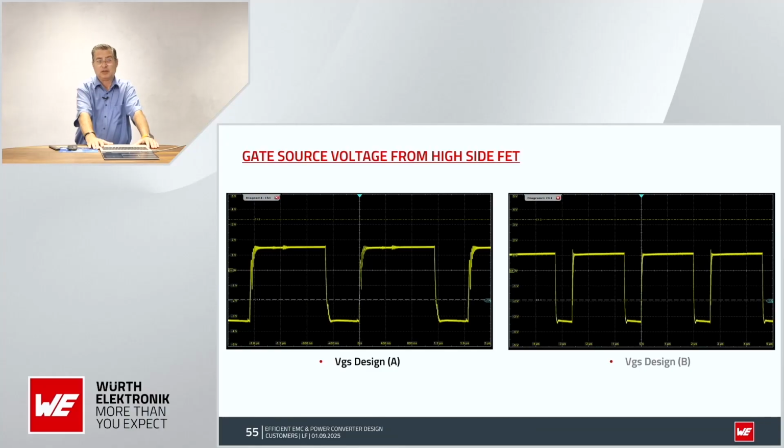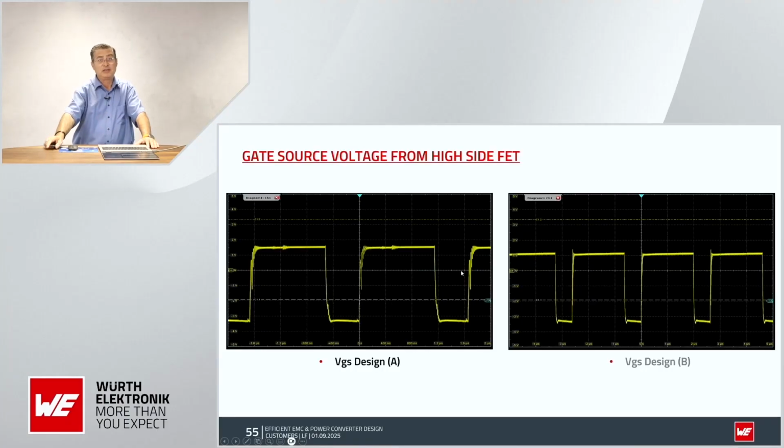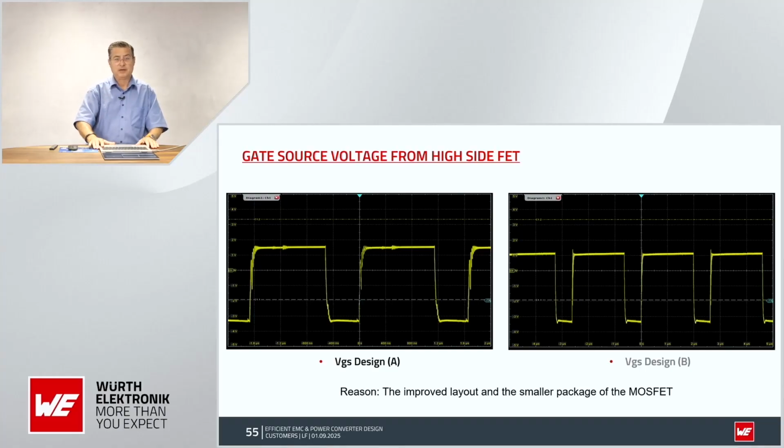This is because of the layout. The layout is different, 4-layer to 6-layer, and also the MOSFETs are different because of the ASL. This is the sign which you see here in this area. Exactly here you can see this ringing. When you switch on, this ringing is the EMC noise. Please avoid such a situation. This is bad EMI.